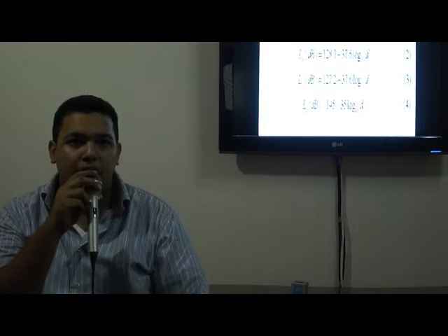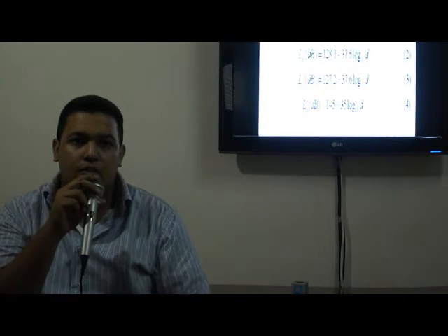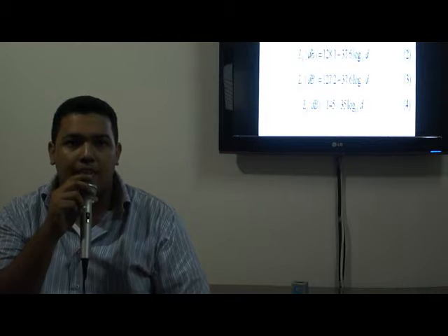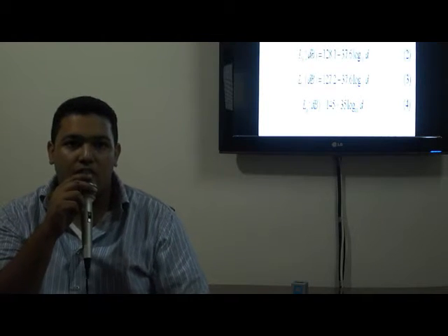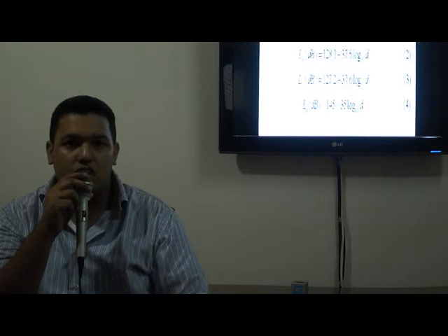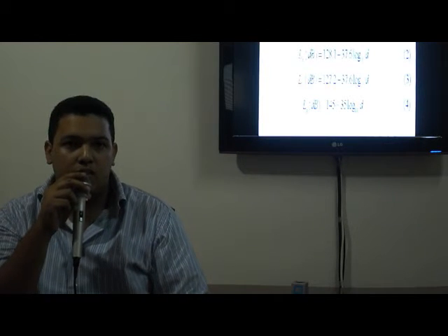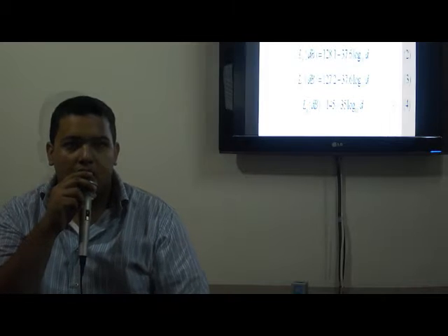The Sphere platform considers an urban or suburban environment, and therefore a standard deviation equal to 6 dB has been established. The shadowing is a spatially correlated process.